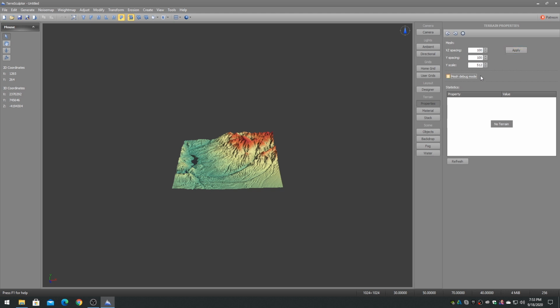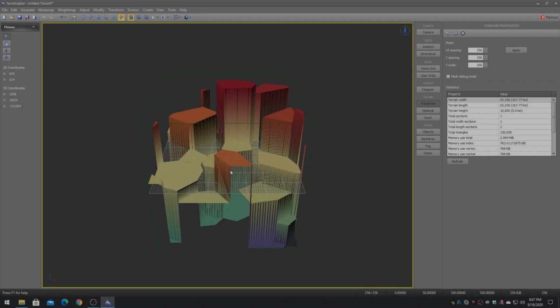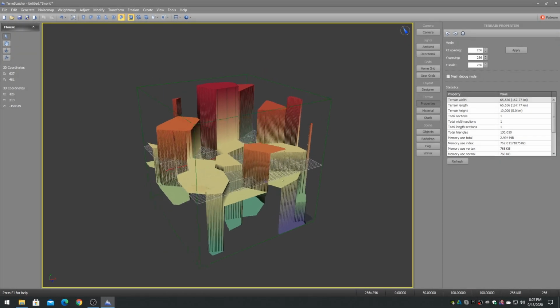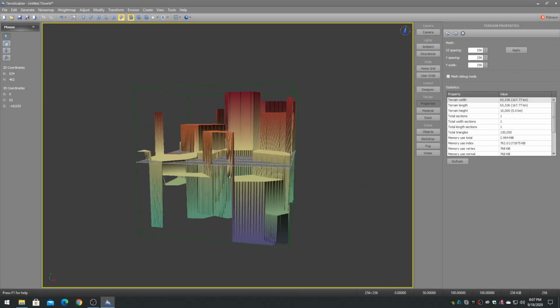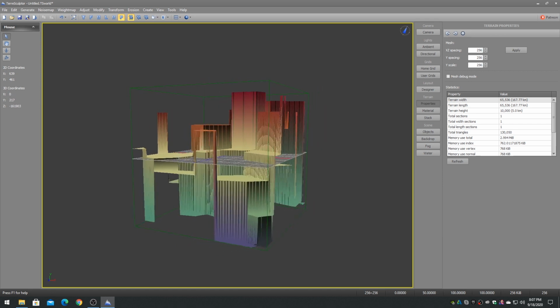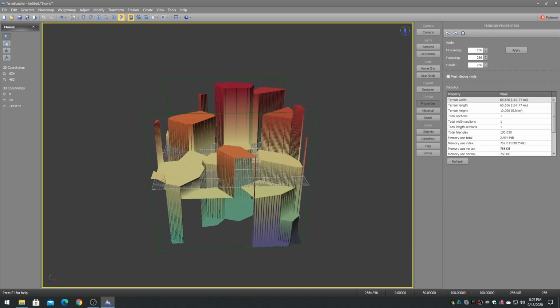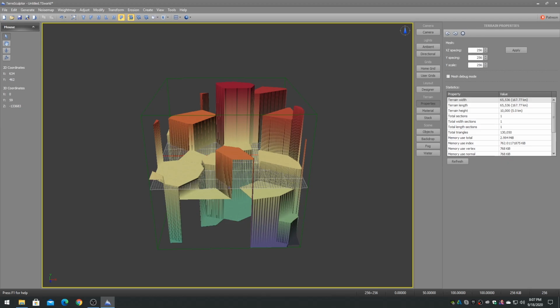TerreSculptor uses the OpenGL Y-up axis 3D world system. The Y-scale value determines how the height map total elevation range is scaled on the Y-axis. This is the ratio of the height map height range versus the mesh height range. A set of spacing and scale values of 256, 256, 256 result in a cubic 256 by 256 height map in the editor 3D world.